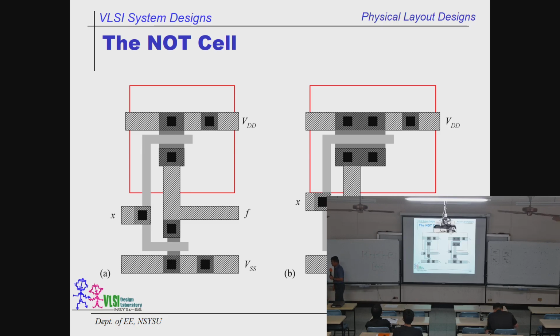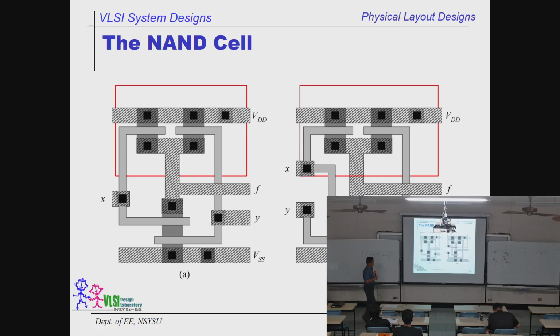Now we are going to check all the sizes of different logic gates. Okay, right now let's check. This is a NAND gate. Let's check the size over here. Why is the size so different from the inverter? So let me put the inverter over here. Right now we have a very clear picture. What is the size for the inverter? We know that we like to have this kind of ratio, 2W over W, or 2W over 1W.